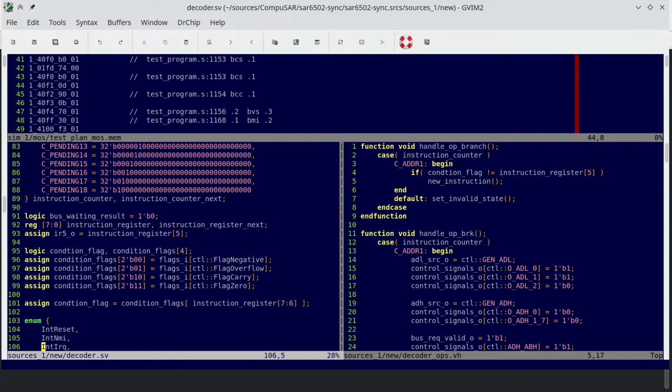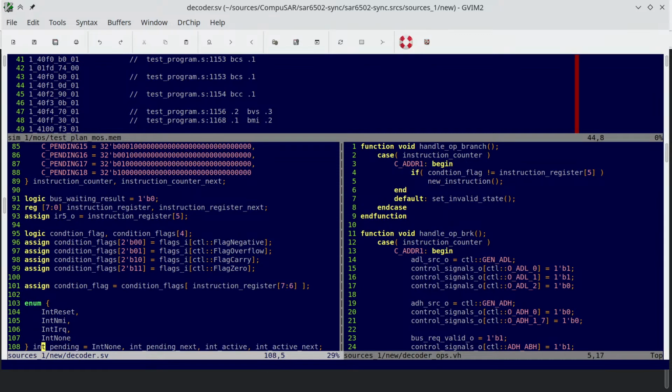Where were we? Okay, so we were reading the opcode, and then we were fetching the first operand, and that was done automatically by the standard logic. But what the standard logic did not do is increase the program counter, because the standard logic doesn't know if the current opcode needs that operand.